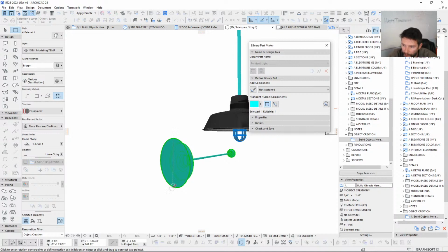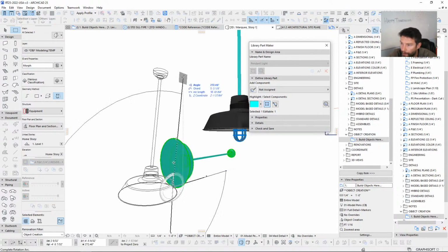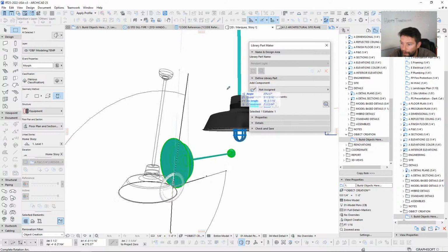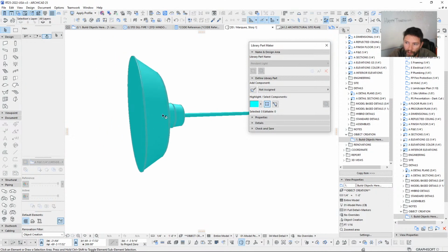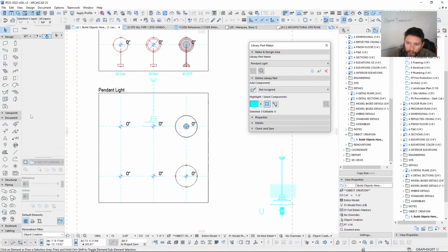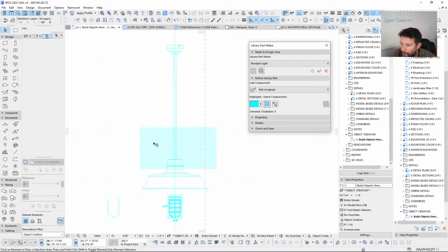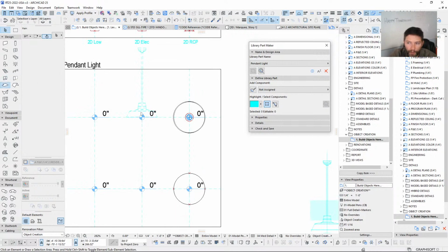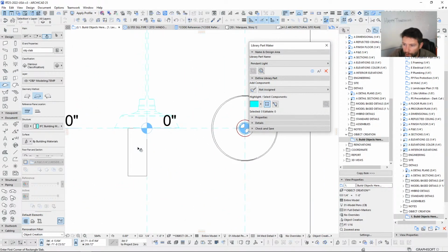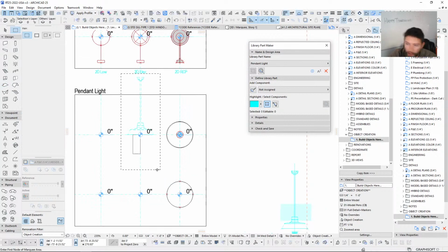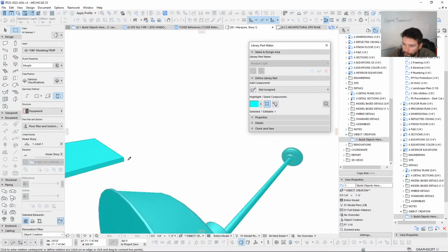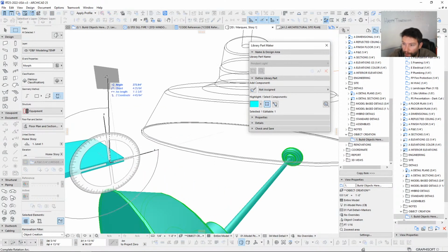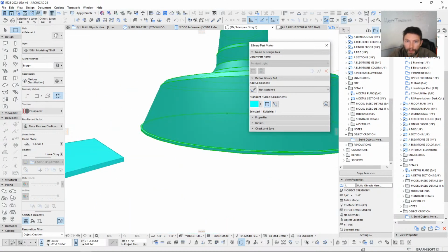It definitely takes a little bit of time to get these working. Now that rotation there, this is one of those situations when you have a rotated element like this with not very many square faces, it does become very difficult to get that rotation exact. Maybe there's just a setting there that I need to figure out, but to get this working a little better, once again, we're going to throw a little reference plane in there, and we can grab this, come onto our face of that and bring it straight up.